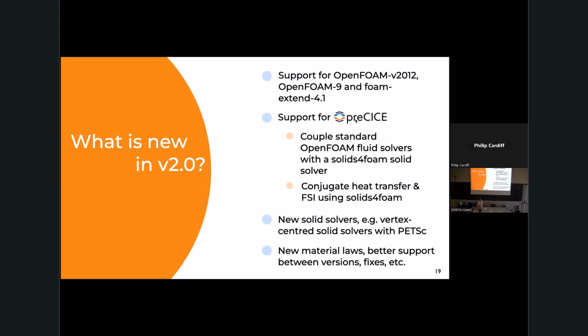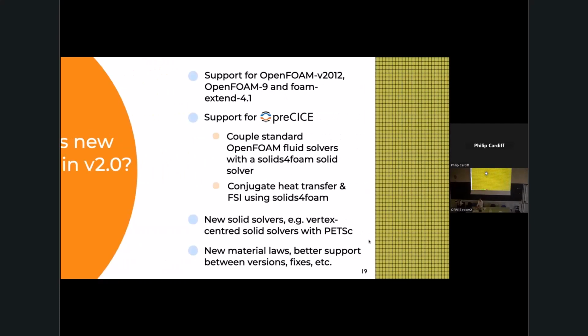Now I worked with the guys there to make an adapter, as they call it, for solids4foam. So now you can use the solids4foam solid solver with a standard OpenFOAM fluid solver if you wanted, or you could couple the solids4foam solid solver with a solids4foam fluid solver. There's no reason to do that, but you could, or solids4foam with another fluid solver. There are also some new solid solvers, vertex-centered finite volume ones based on the PETSc linear library, new material laws, bug fixes, etc.